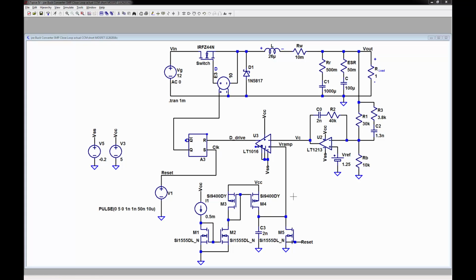So what's happening is that we want a ramp here. How do we create a ramp? Well, a ramp is created by a constant current source. We want a constant ramp, a constant current source into a capacitor. Don't worry about the switch. This switch only turns on when the clock hits. When the clock goes up and pulls back, you can see the clock width is 50 nanoseconds. It goes up and down. It'll discharge that cap down to 0. So it starts at 0. And then what? When it releases, it's an open. And what do we see? We see this constant current going into this cap, and we should see a ramp circuit. And we will see that.